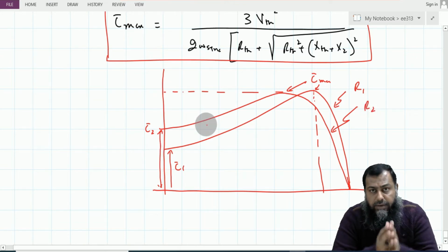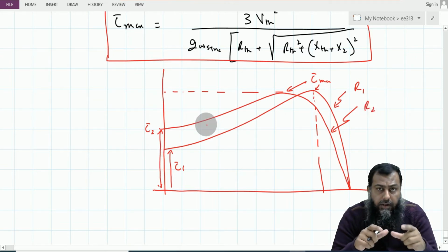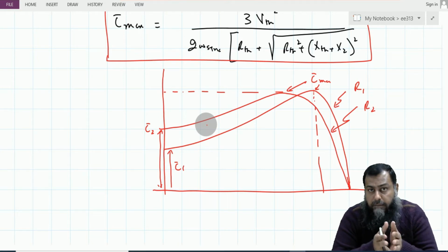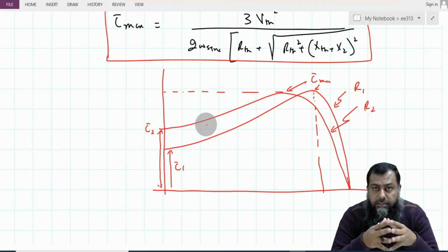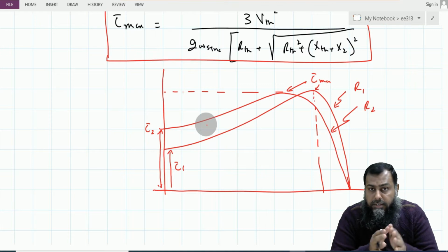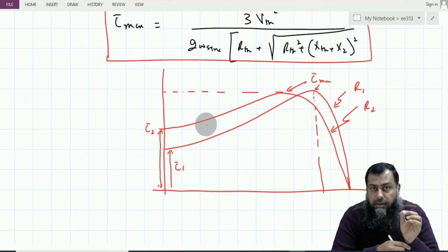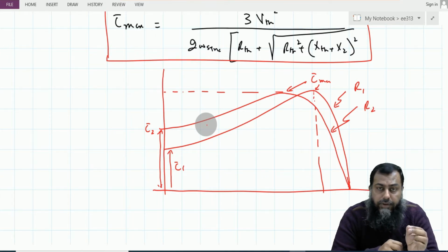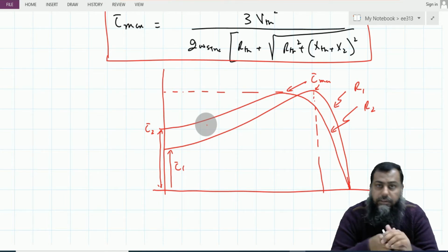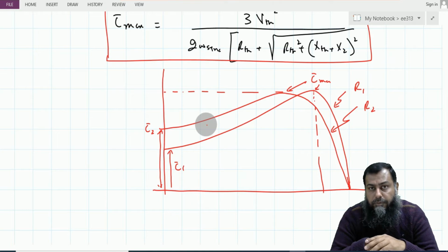So what we are inferring here is that if a motor is provided a load that requires a higher amount of torque, then the same motor can be utilized by inserting external resistances into the rotor circuit. And this is only possible for the wound rotor induction motor, where we have arrangements for external connections with the rotor circuit. It is not possible with the squirrel cage induction motor.